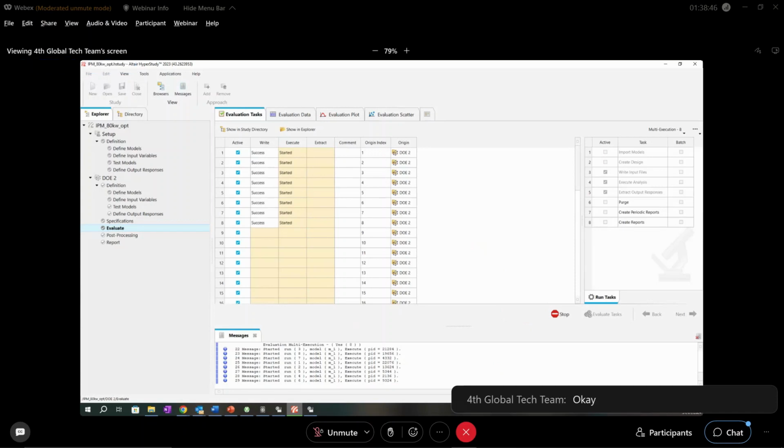Okay, some of the runs will fail due to invalid geometry for some combinations of the input parameters, as I told you before. It's not a problem, it's fine. I mean, it's expected, so don't worry. For this case, 4 out of the 15 runs normally failed in my test, so no problem.